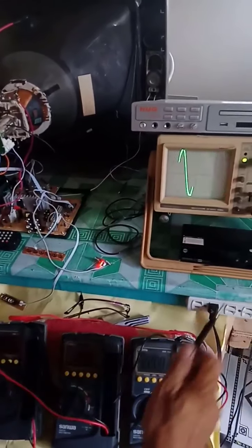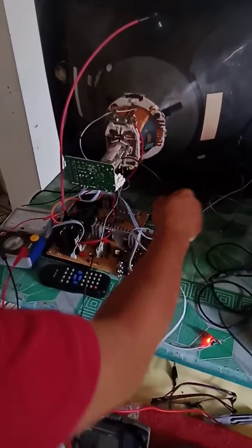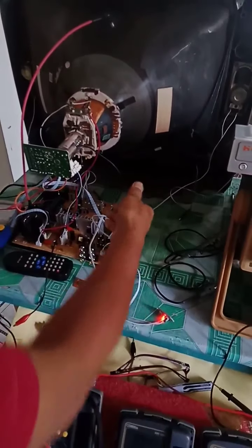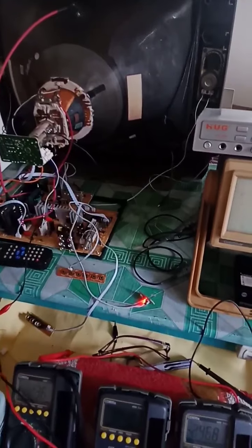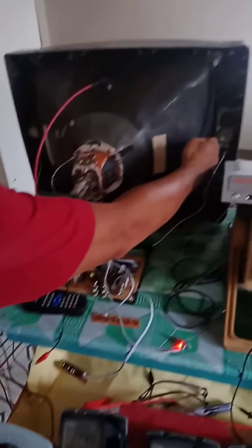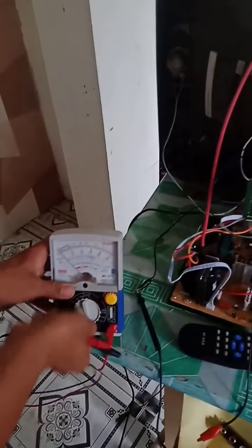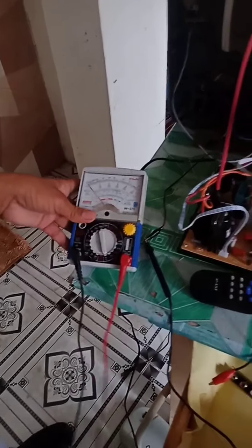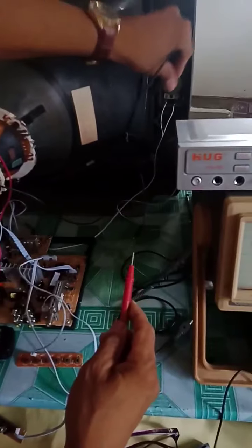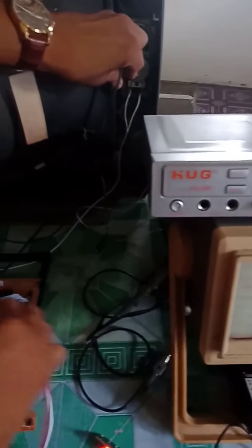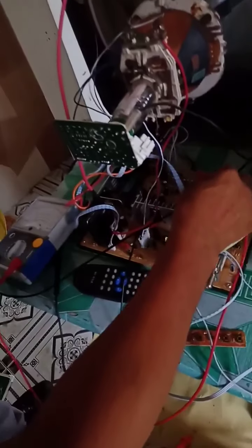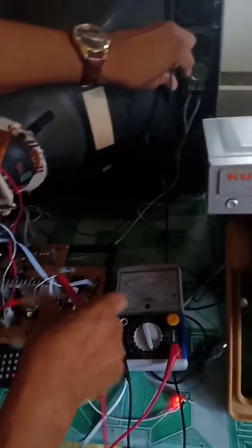You can also connect the negative of the DC voltmeter to the metals of this. The metals, okay. How can we prove that the bare harness wire is connected to these three metals? By means of a continuity tester. Using this analog meter, set it to times 1 for measuring continuity. Okay, we have here. Okay, it deflects, right? We have here.